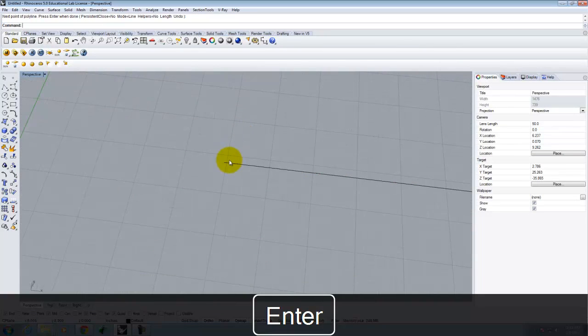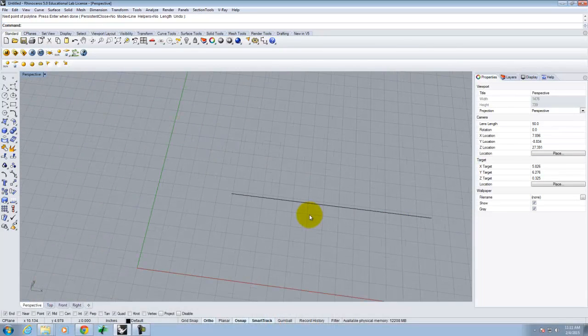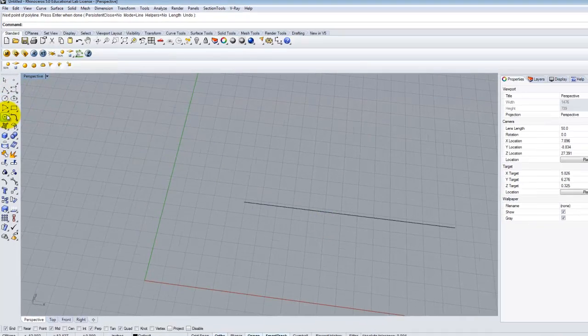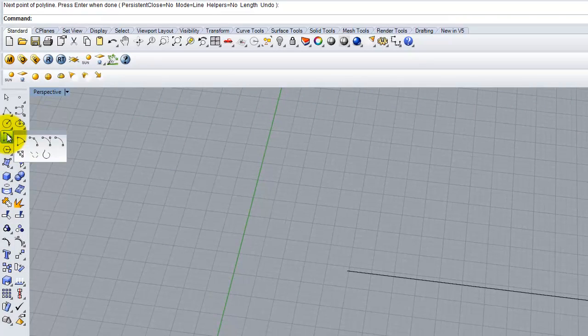Now on either end of this, I have 2 arcs, which have a radius of 2 inches. So I'm going to need to do 2 arcs. And it's useful when you're doing the arcs to go ahead and click on the arc tool and then see what types of arcs we can do. Right? So we have an arc with a start, an end, and a radius.